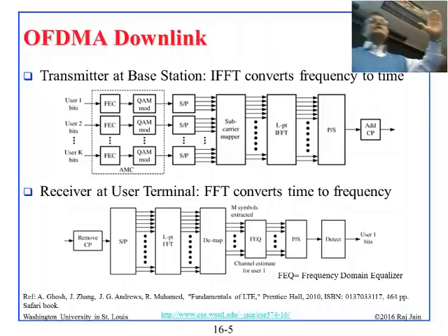What that means is that these are your subcarriers, but the ones that go on the air may not be in the same order. The order is randomized in some way. Actually it is a fixed mapping, but basically the first carrier may go there, the second carrier may go there, and the third carrier, and so on. That way, if some noise hits some carriers, it doesn't hit the same user. The noise is distributed among many different users because now the users are all over.